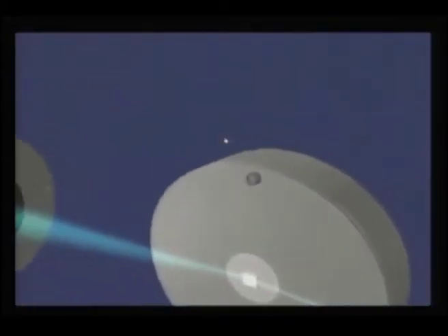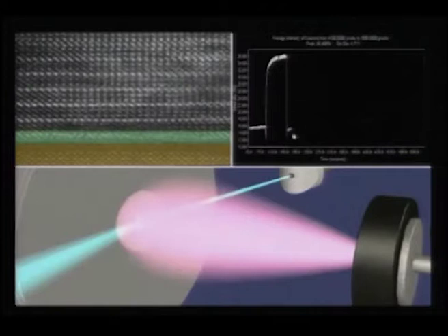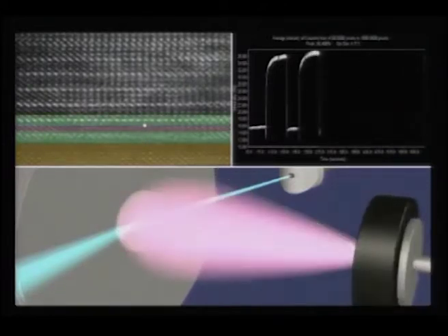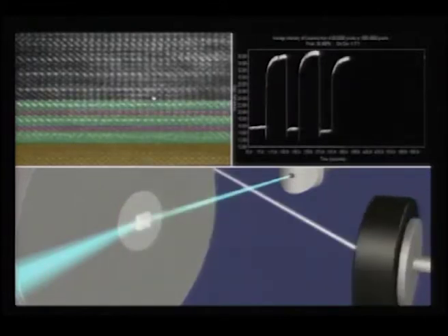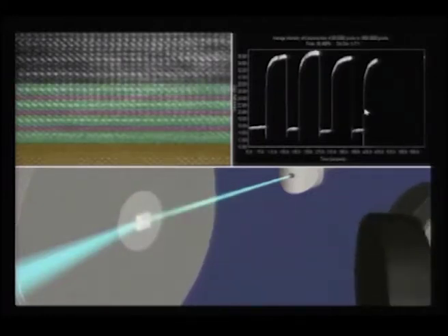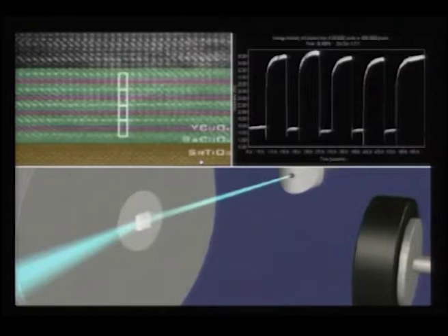So in this cartoon, the RHEED diffraction spots are there, and those spots will tell you whether you are really doing a layer by layer growth. As a result, you can see that this sort of oscillation comes depending on the way you are trying to coat the material. So you can make these stackings alternately using RHEED oscillation, and that way you can control and make a periodic deposition of a superconductor.